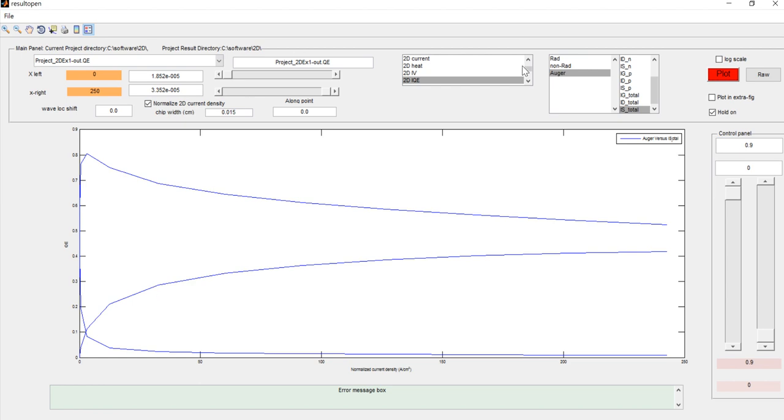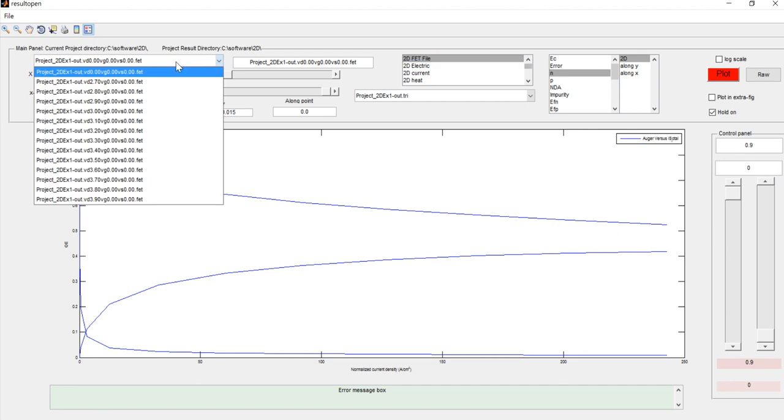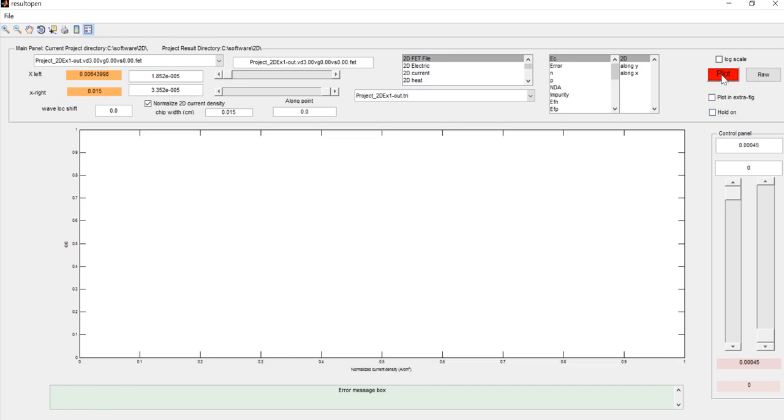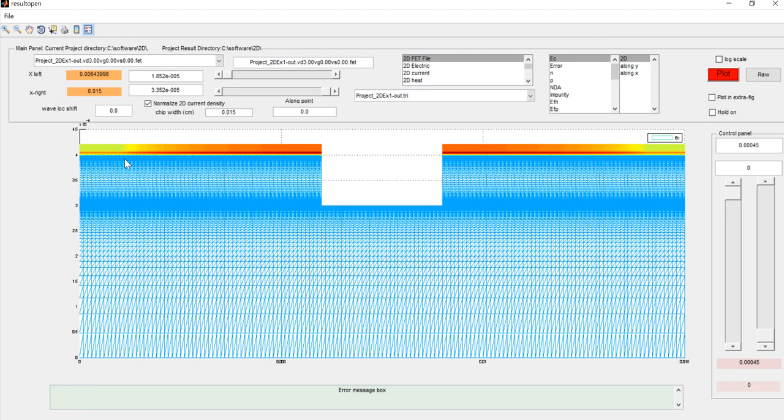Okay. Alright, so we can go back to look at the FET. Let's say at 3.0, plot EC. The thing is normal, just like this. Look at here, the contact is here, and the contact is here. There's a field in this direction. Okay. Then most importantly, we'll look at the radiative recombination rate, because it tells us where the electron and hole recombine laterally.